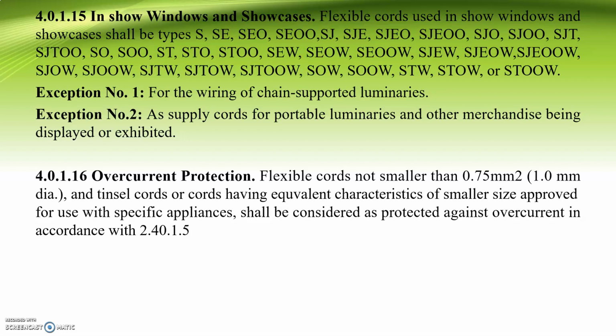Chapter 4.0.1.16, overcurrent protection. Flexible cords not smaller than 0.75 mm squared or 1.0 mm diameter, and tinsel cords or cords having equivalent characteristics of smaller size approved for use with specific appliances, shall be considered as protected against overcurrent in accordance with Chapter 2.40.1.5.